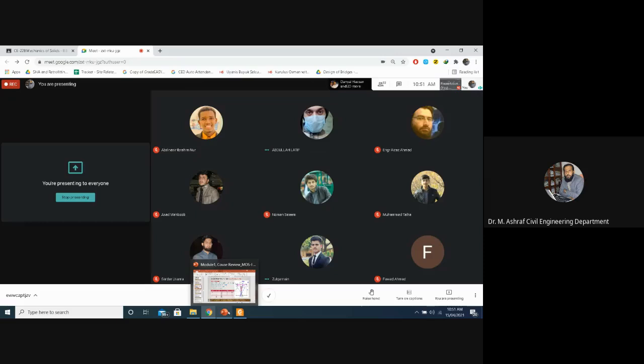नहीं, आप उसकी बात कर रहे हैं कि कोई कंपोजिट सेक्शन है या एक सेक्शन है? तो हम उसमें समेशन तो नहीं लेते ना। एक सेक्शन है तो सिंपल है। If you know the radius of gyration and if you know the mass of the section, so mr square will give you the mass moment of inertia of that section. ओके, या अगर एरिया है तो बस आपको एरिया दे देगा।